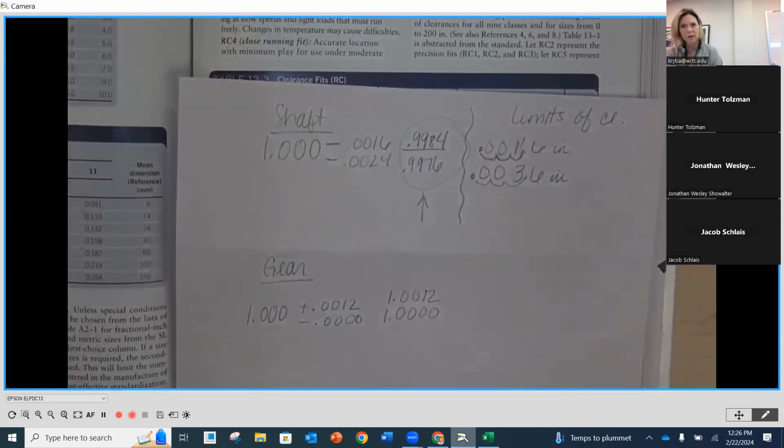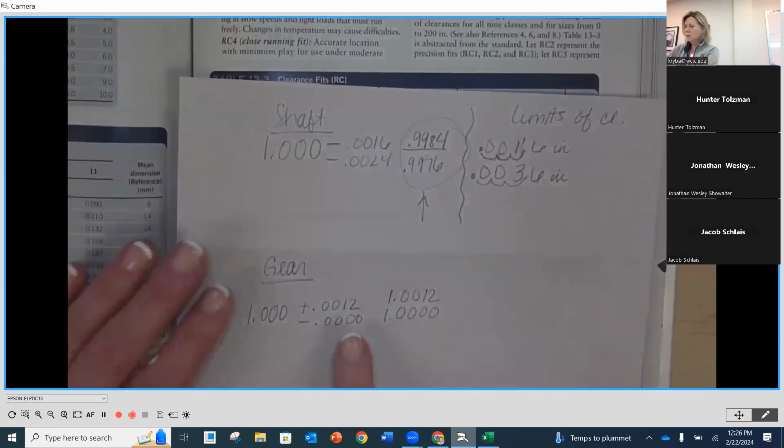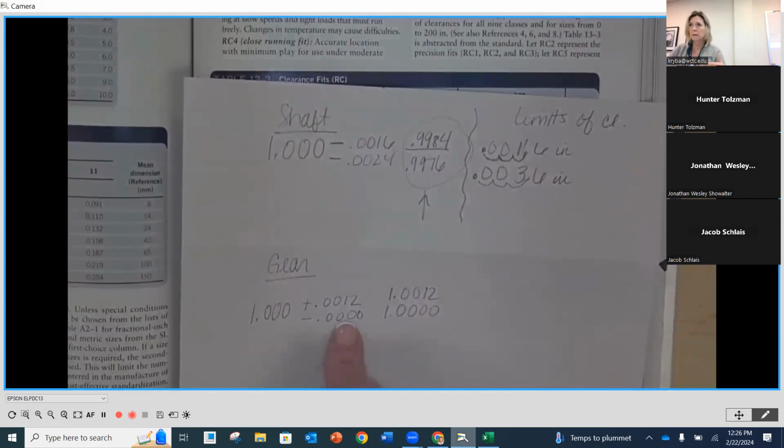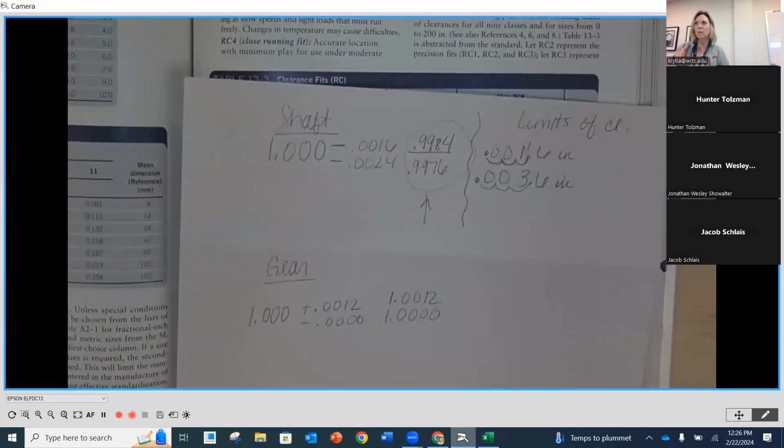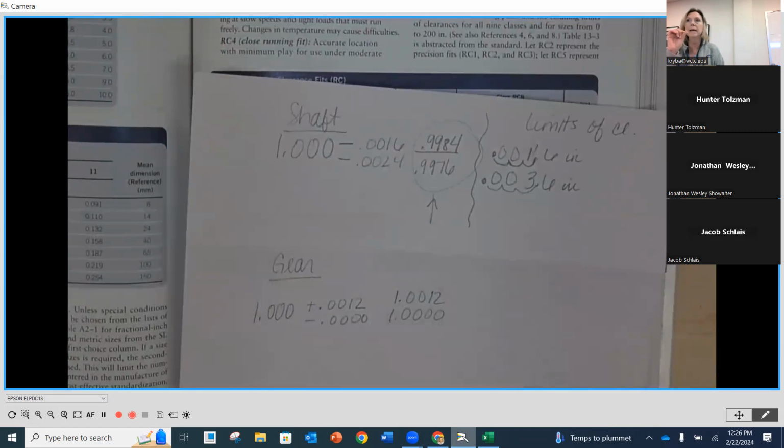There you go. Think about the tools we're going to be using to manufacture these features. You can get a drill or a boring tool that's 1 inch nominal, right? And on a shaft, I can simply go in and out with my tool on a lathe, and make it smaller or larger to whatever number I need. So this is called the basic hole system, and that's how all of these charts are set up, so that your nominal will always be on the hole size.